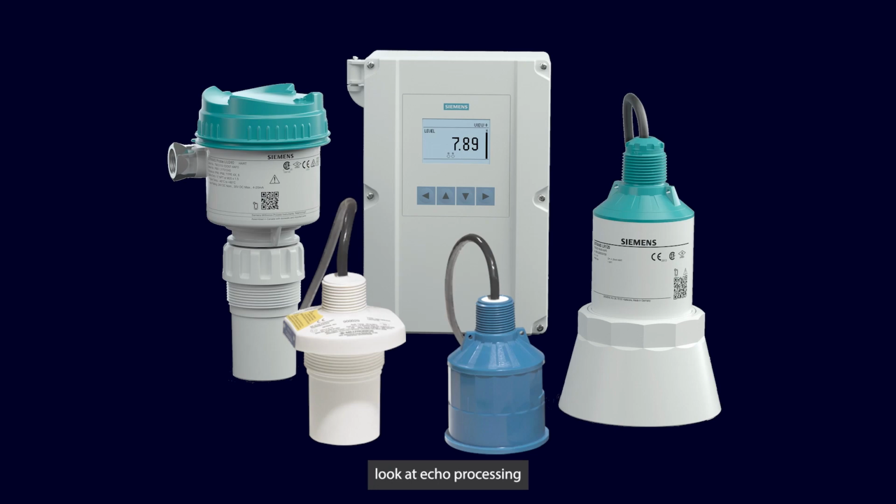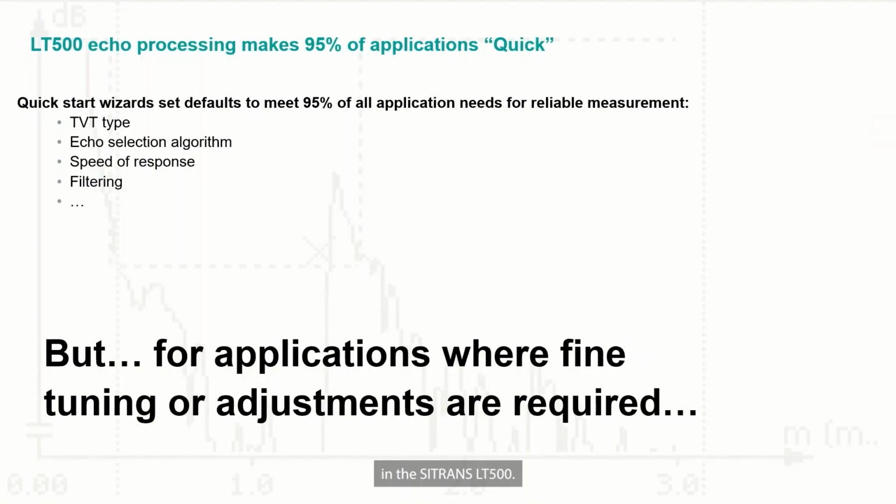Let's take a closer look at echo processing in the SITRANS LT500. Quick Start Wizards can ideally set everything up so that 95% of the applications that are out there will provide reliable measurement just running the Quick Start Wizard, and you can walk away. That'll set your TVT type, your algorithms, your filtering, all of that stuff is done through the Quick Start Wizard. And like I said, that'll take care of most applications that are out there.